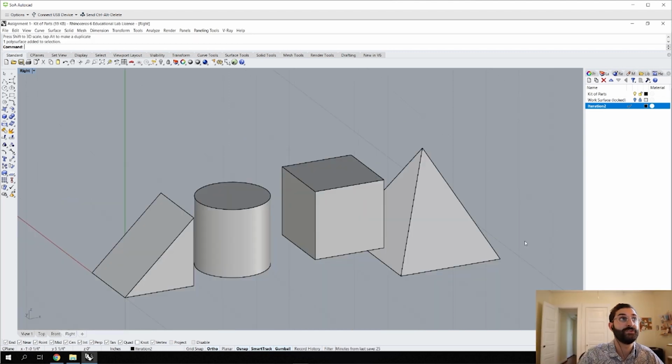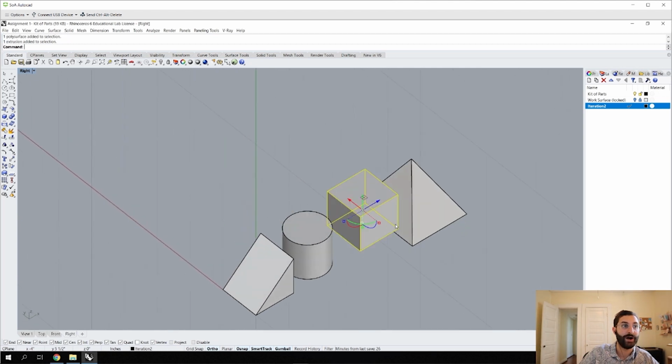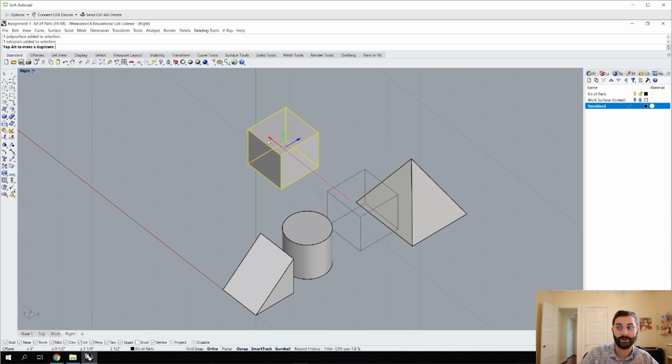Another important thing to consider is copying and pasting objects. In the tutorial, you're going to need to have at least a total of 10 objects. So there's a couple ways to do that. We can continue to use the Gumball for that operation by, when you have an object selected and you're moving it, you can use the Alt key on your keyboard to click it, and then there's this box next to it with the plus sign pops up, and that shows that you're creating a copy. So if I click Alt again, it'll go away. So clicking Alt and let go, it'll create a copy.